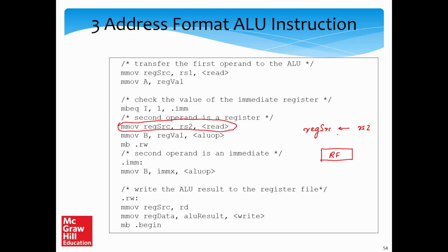Why are we doing that? Because the command is being sent via the bus, via the args field of the bus, to the register file to either read or write. In this case, it is read. Doesn't matter, it can be read or write. Since a command is being sent, we'll activate the register file. And since it's a read operation, we will read the data from the reg source micro register. So we allow a concurrent writing of this micro register and also reading of its value.